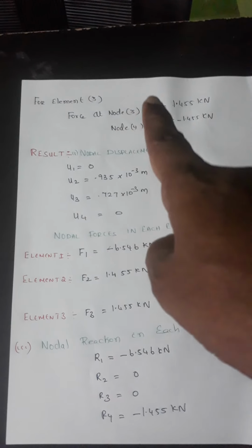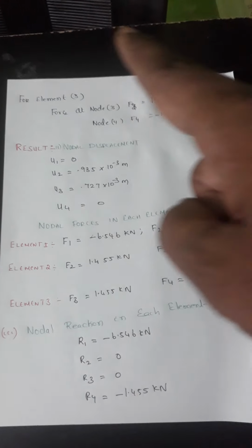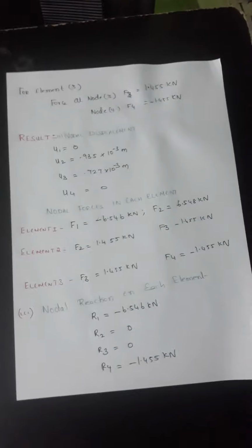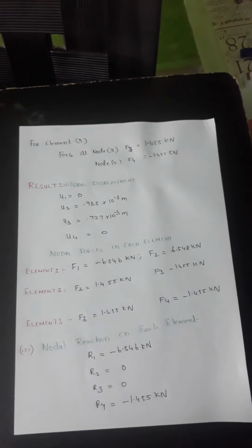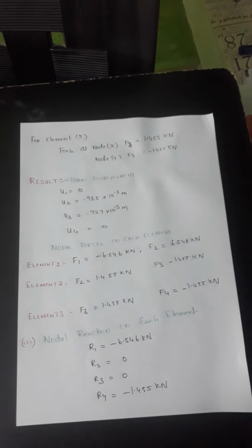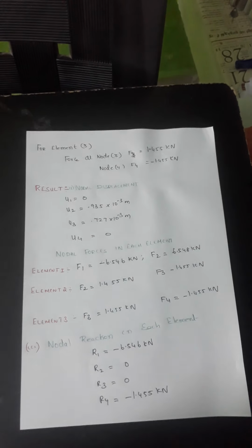So the forces at node 3 and node 4, the complete result I have written. And one more point: even if self weight is not neglected and the body force is given, you have to find both the body force and the nodal force. If they ask that self weight is not neglected, they have asked for the body forces also and the nodal forces also, then you have to find them.